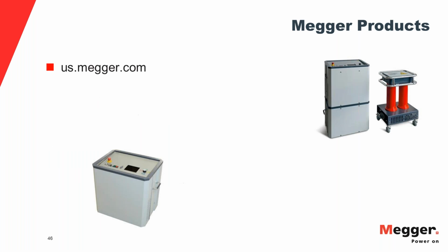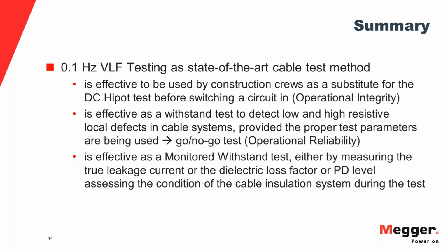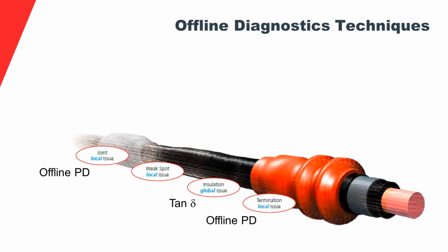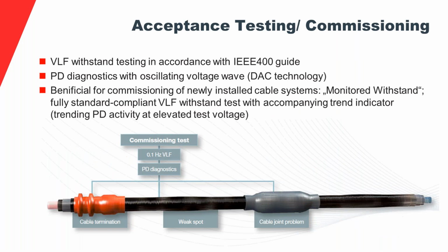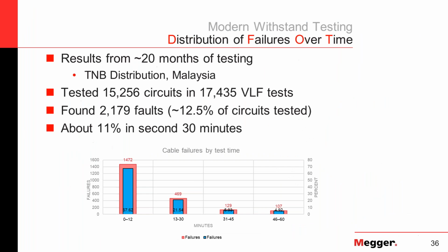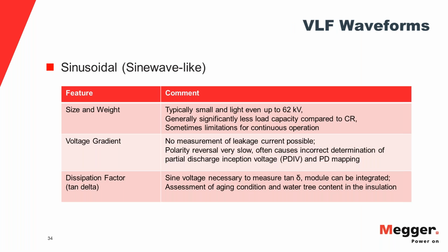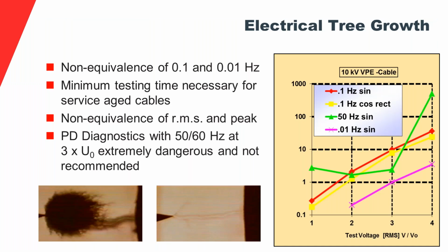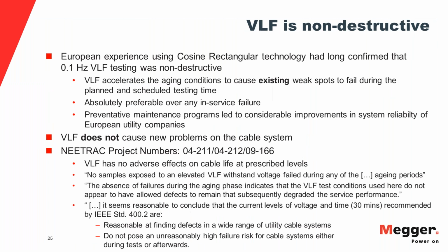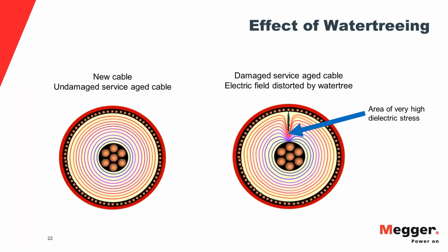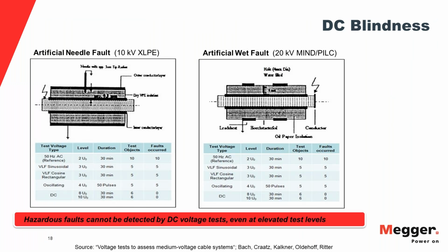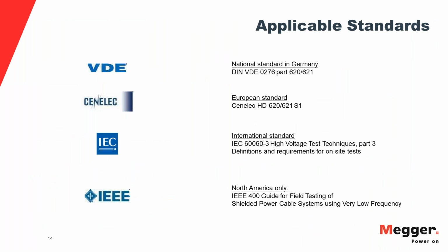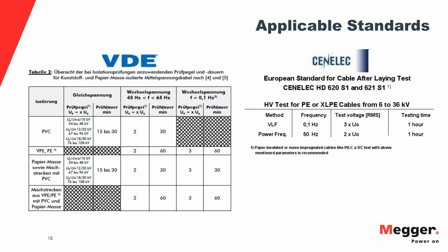In relation to the insulation resistance test, you're looking for different things in a lot of these cases. There's a lot of things to kind of unpack with this question, but yeah, the VLF test is going to give you a lot of confidence that that cable will stay in service in the case of a ground fault like Robert was describing, or a lot of confidence in the overall quality of that cable, where the insulation resistance test, maybe less so. It doesn't put as much of a voltage out there.